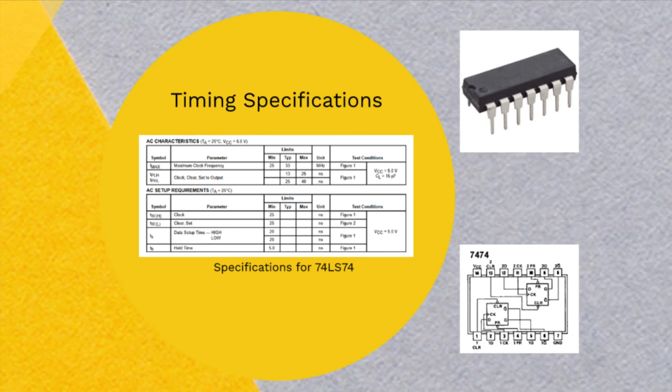The final task of this lab was to research and become familiar with specification sheets, or data sheets, that give us the various delays inherent in different circuits. These specifications may include propagation delay, setup time, hold time, and guaranteed frequency. The key takeaway from this portion of the lab was to understand that different components have different limitations and boundaries within which they can operate correctly in digital circuits, and it's important to be aware of the limitations of a given circuit when designing real-world applications.